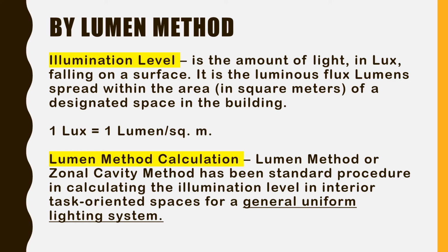Lumen method of calculation is also called the zonal cavity method. This is the other name. It has been the standard procedure in calculating the illumination level in interior task-oriented spaces. Take note, in interior task-oriented spaces for a general uniform lighting system. It is clear.